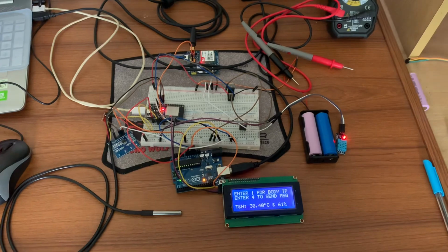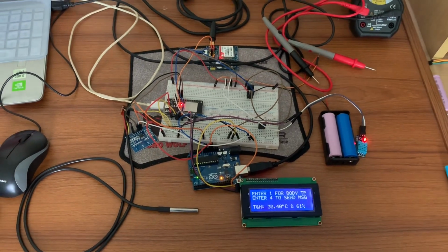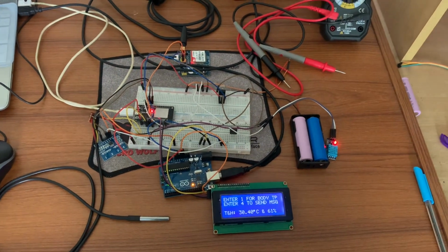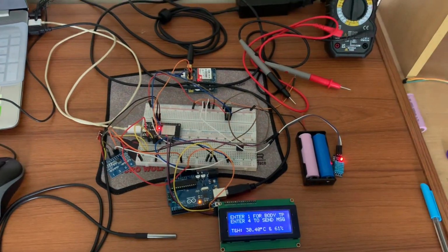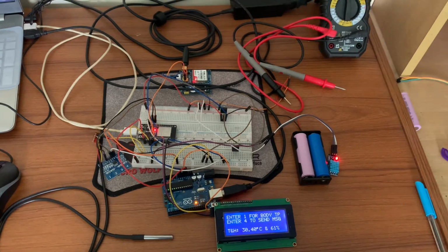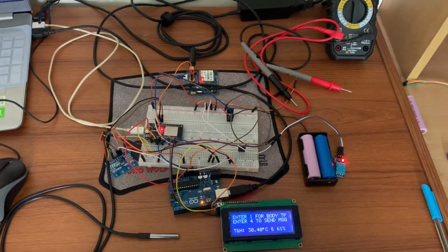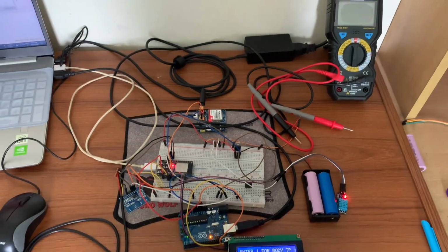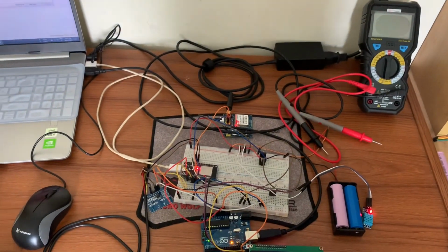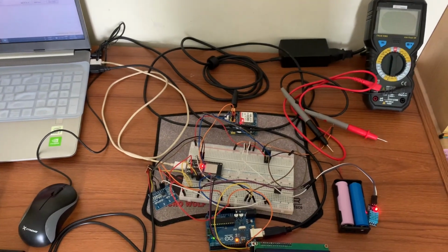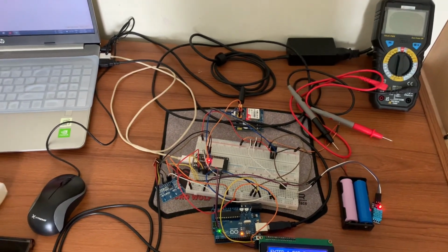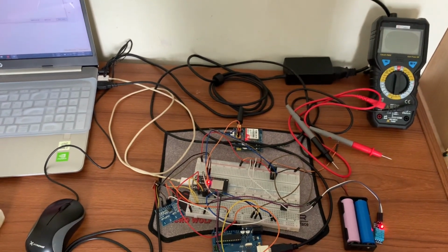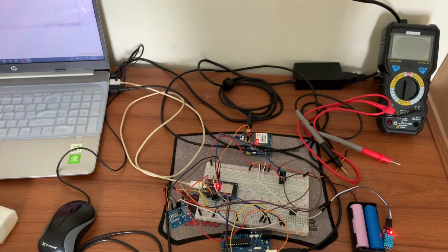That's because the memory of the microcontroller cannot take the load of the entire project. I will be describing the reason why. Well, that's because the measurement of the blood oxygen level works on the basis of the collection of a number of samples from the MAX30102 sensor. It has to collect samples of unsigned long integer type, and in 4 seconds the sensor extracts around 100 samples. Each of these samples is of unsigned long integer type.